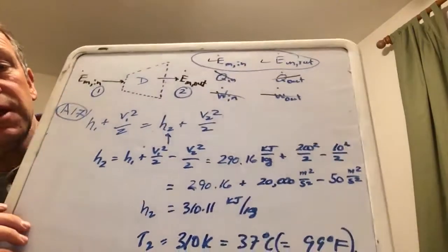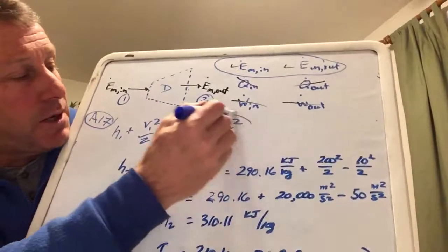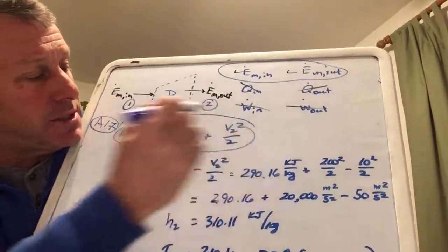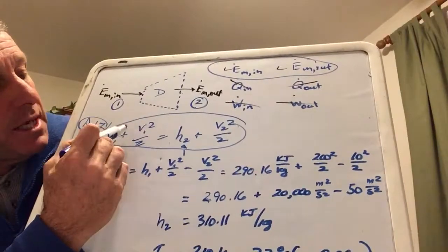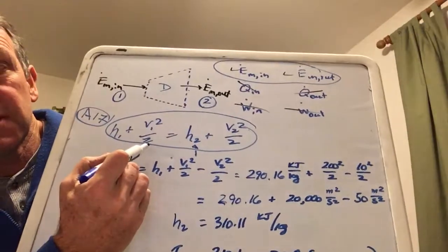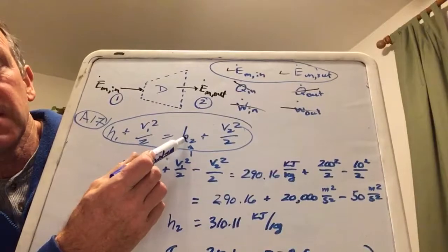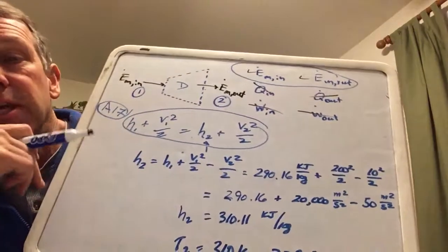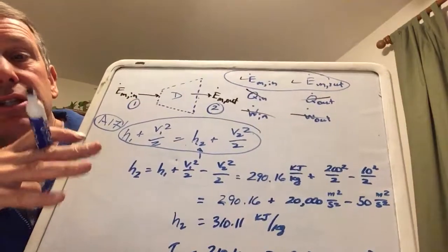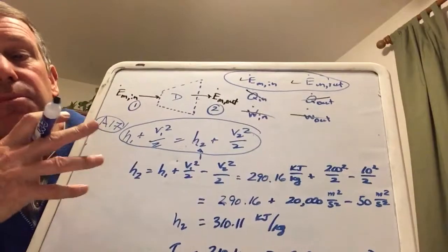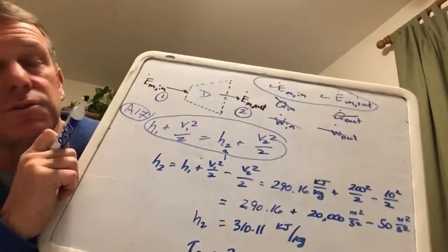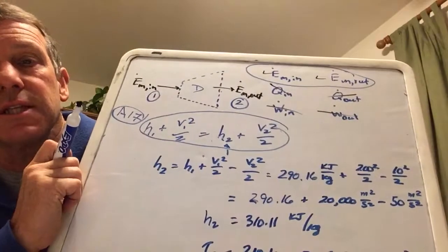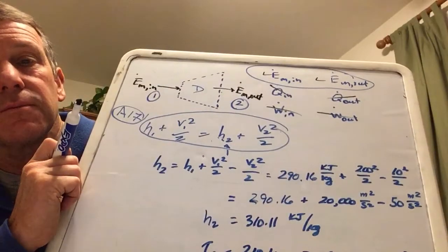Well, if you take a look at what essentially this equation right here could be saying to us, as it goes through, it ends up losing this kinetic energy, and that becomes enthalpy. That becomes actual energy of the air. So kinetic energy is lost, and it becomes enthalpy energy of the air. And enthalpy energy corresponds to temperature energy in a sense, and so the temperature actually rises.